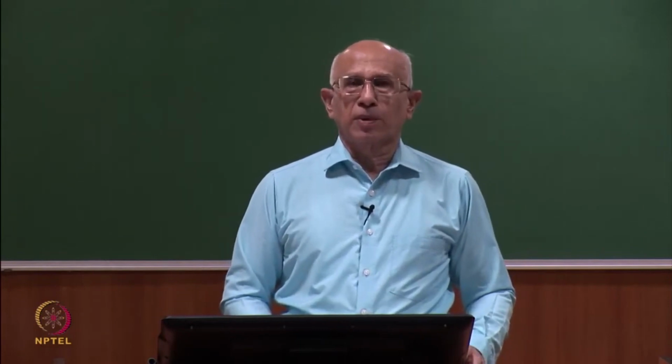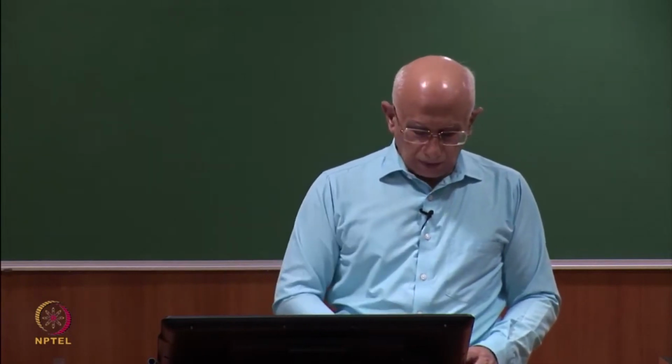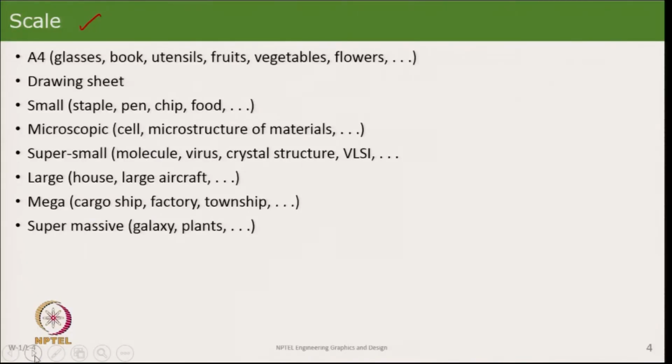So, let us begin with some aspect of a drawing, which is what is called the scale or the scaling. So, what do we mean by scale? It is that we see objects and we see them in relation to some other size. In making drawing sketches and in engineering, our standard is a drawing sheet, which, as a standard sheet that we look at, is an A4 sheet. A4 sheet is an Indian and international standard which tells you that the size of the sheet is 210 millimeters by 297 millimeters.